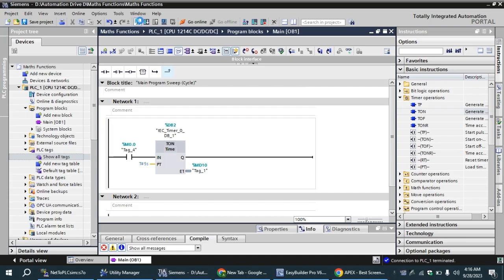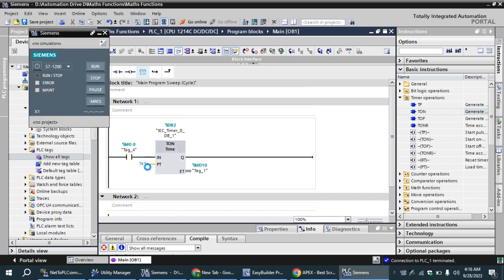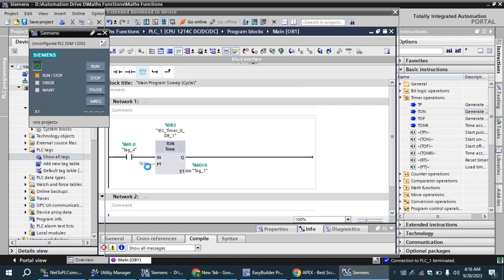When you run this timer, actually, when we give this preset value data register bit in the HMI, then we need to give the time in milliseconds. For example, if I give 1 second, we have to put 1000 in the numerics in HMI.